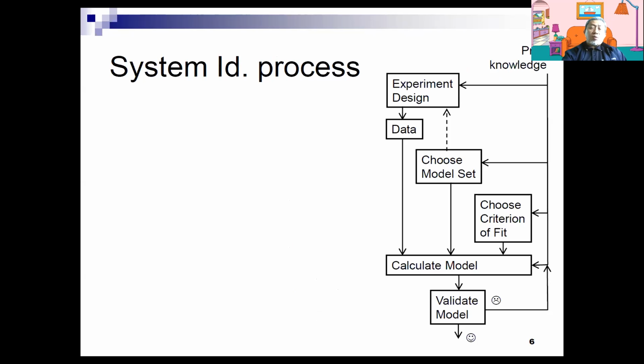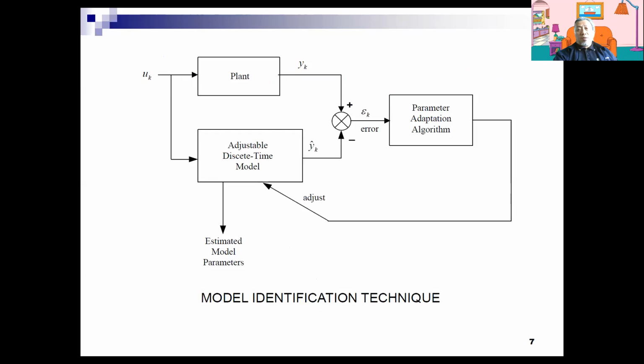This is the process that we have to carry out during the experiment. To set up the experiment takes time, but to capture the data takes maybe about 2 minutes or 5 minutes, depending on how long the data is and the sampling time that you design. And then the important thing is to estimate the parameters of the transfer functions, the coefficients of it.